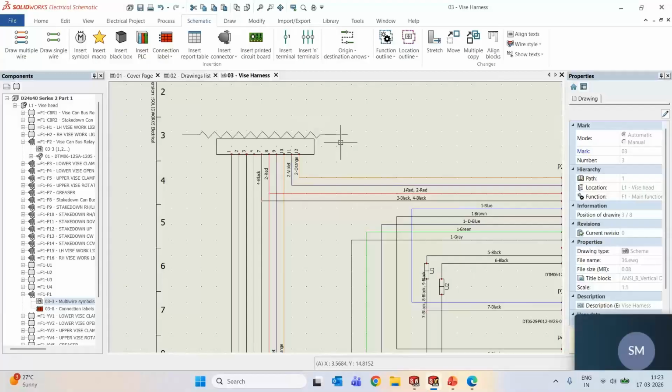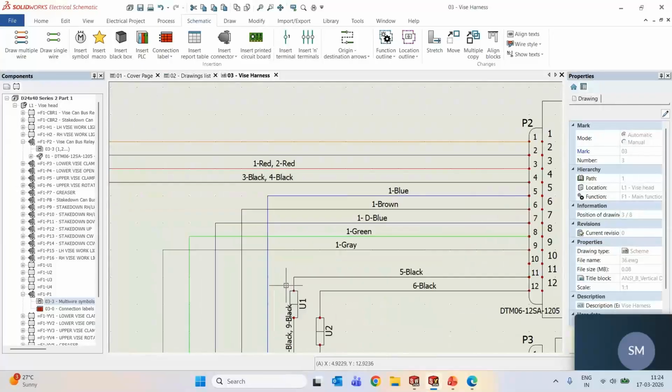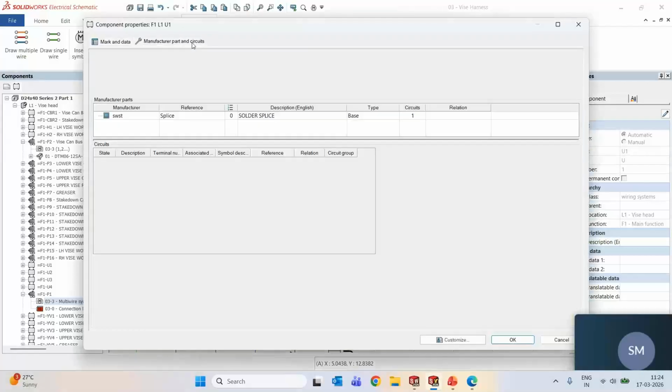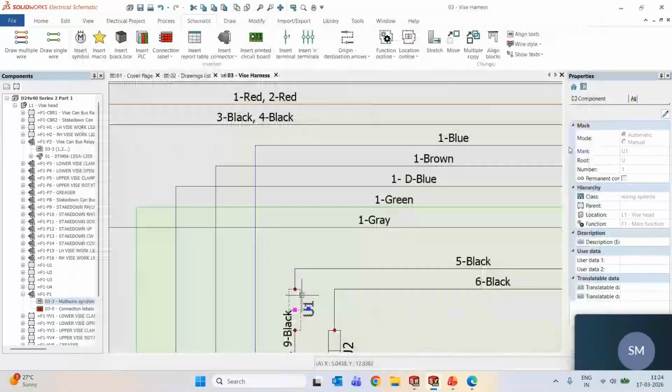So with the help of all of this, we were able to identify that accessories can be added to the manufacturing parts and to the terminals. So we don't have to model that particular symbol. We can just add the accessory as a manufacturing part and we will be able to utilize this. So without a manufacturing part, SolidWorks Electrical does not work, because the SolidWorks mechanical integration, whatever we do, it is through the manufacturing part. So every component in here should have some manufacturing part attached to it. You can see here. So like this.